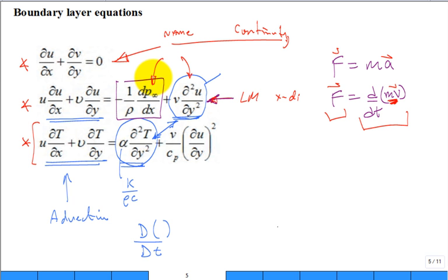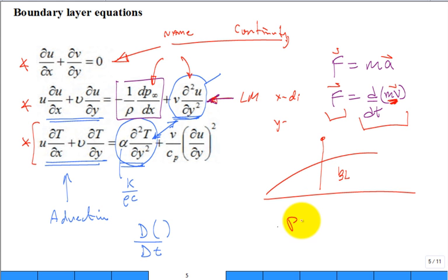Pressure gradients. Now they didn't write down the y equation for linear momentum because it boils down to this: the pressure external to the boundary layer penetrates the boundary layer, and the pressure, which in general could be a function of x and y, is, for the boundary layer over a sharp edge plate, a function of x only. Hence, the partial derivative of pressure with respect to x boils down to the ordinary derivative of the pressure far away with respect to x. So there's a lot of discussion in here which I'm glossing over. It's fluid mechanics, and I know that's in the fluids book as well.